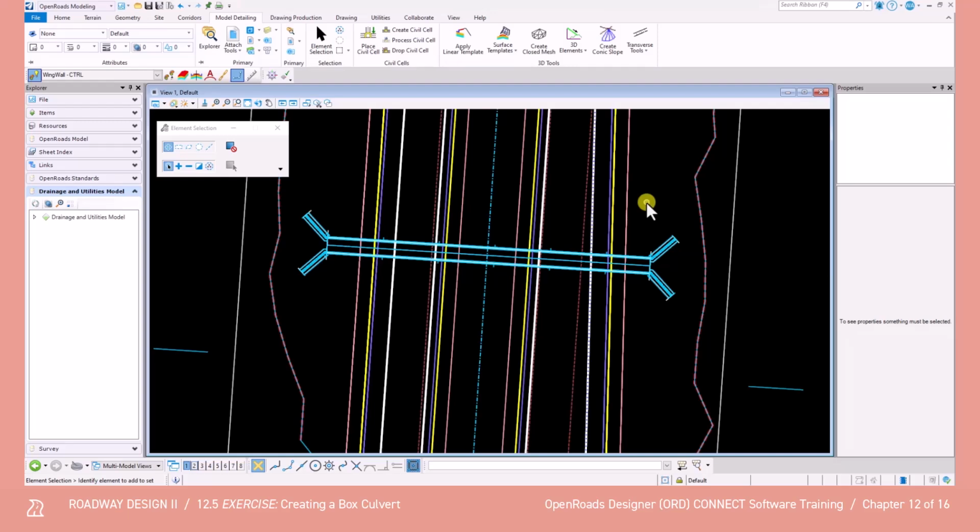Then from the Standard Drawing 17-15, we can see the wall dimensions for both the 6-foot and 10-foot design heights, and then the dimensions that go along with both of those. And that's where we're going to be transitioning from the 10-foot here to the 6-foot on the outside edges.